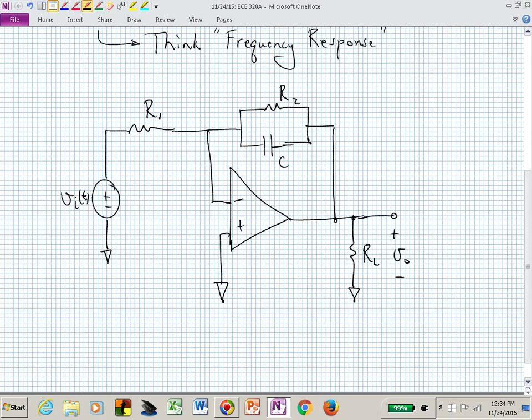When you see that circuit, do you think of any particular behavior without even doing any kind of analysis? If not, then let's do some analysis, but this is actually a low-pass filter. What's the order of that low-pass filter, if you had to guess? First order, because we have one energy storage device. What I'm not showing are the power supplies that are energizing that op-amp. This is an active circuit versus the passive circuits that we have played with before.